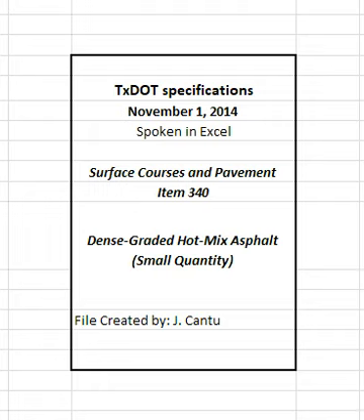4.9.4 Placement Testing. The engineer may measure in-place air voids at any time during the project to verify specification compliance. 4.9.4.1 In-place air voids. The engineer will measure in-place air voids in accordance with Tex-207-F and Tex-227-F. Cores not meeting the height requirements in Table 12 will not be tested.